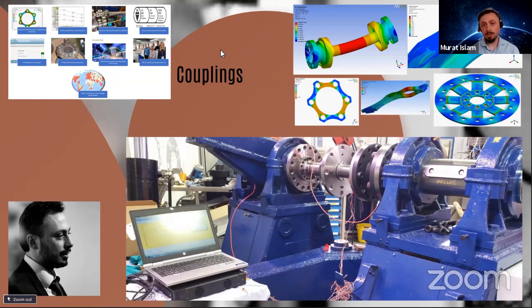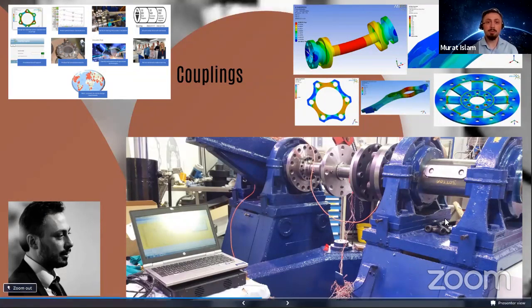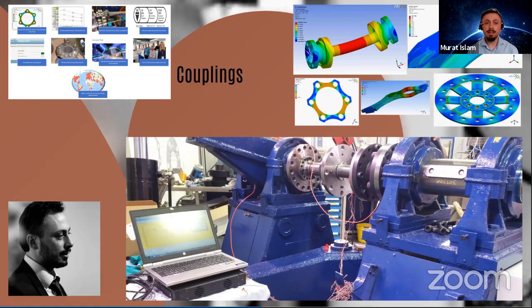Like Kyle mentioned, we also have to do some destruction tests at times just to make sure the maximum capacity is very well defined. Because you will get some statistical results from all the experiments you run. And you just need to rely on the lowest value you get and maybe apply some safety factors on them to have a safe design in actual operation.